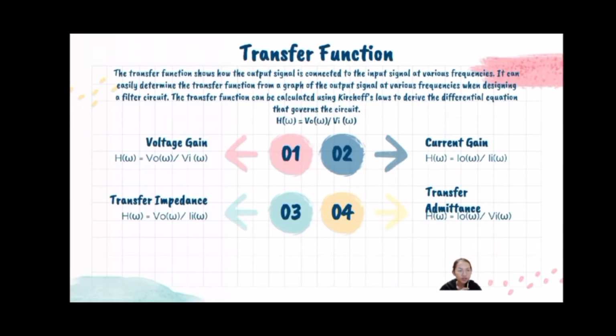So what is a transfer function? A transfer function shows how the output signal is connected to the input signal at various frequencies. You can easily determine the transfer function from a graph of the output signal at various frequencies when designing a filter circuit. The transfer function can be calculated using Kirchhoff's law to derive the differential equation that governs the circuit.